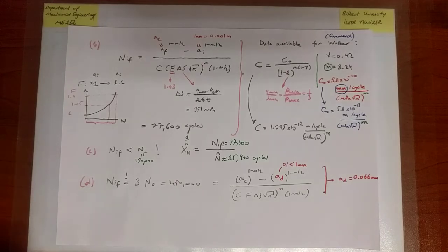If the guy that operates your design says that, no, I don't want to do any service, the only thing remaining is that you have to change your design so that the loads are smaller and therefore the crack growth rates are smaller, and therefore you can actually reach the desired goal with this resolution of the instrument. So this type of analysis allows us not only to determine service lives, certain requirements on application of your structural design, but also on how you should possibly modify your design.